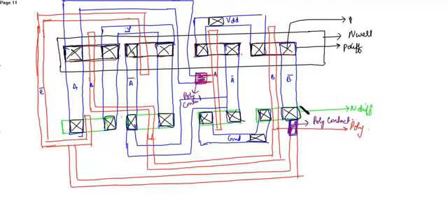Now after placing the contacts, you can just verify once more whether all the connections are done. Inputs given, output is labeled, VDD, ground. Okay, so these are the two inverters. These two are inverter 1, inverter 2, transmission gate 1, transmission gate 2.